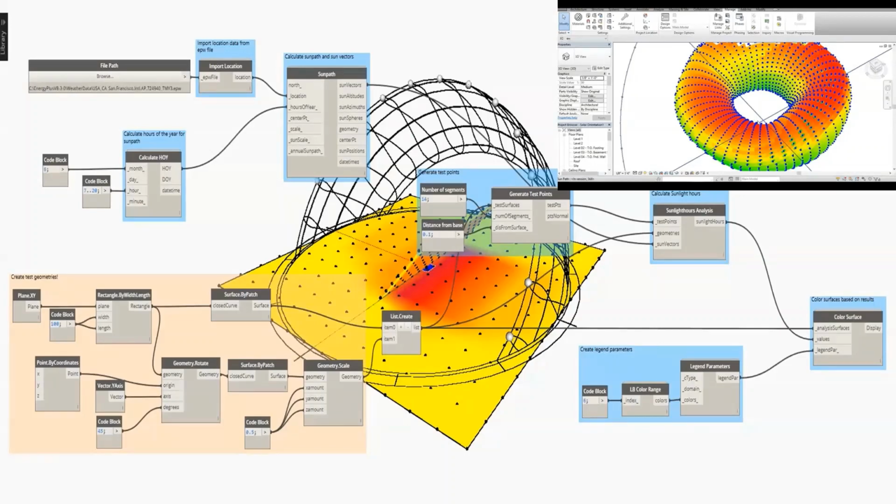Repetitive tasks will be there in our workflow, right? Just like creating a sheet. If I have 100 sheets in my project, with respect to an Excel sheet, I can just create all the sheets, with all the information, within seconds. It's very easy. You just have to create a script. Whatever we create in Dynamo will be called a script. We just have to create that and run it. And automatically, all these 100 sheets, or whatever the number of sheets, will be created. So it's just an example of a repetitive task. You can automate things. That is one of the functions of this visual programming.